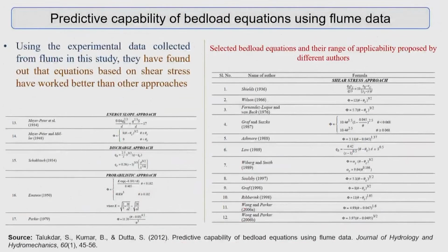Now, what are the equations? There are so many equations on bed load. If you look at the very old 1936 DuBoys equation, it is basically a shear stress based approach. There are many methodologies based on shear stress approaches, with certain assumptions. Like Grass 1998, a very simple equation, it just depends upon theta and theta c, the Shields parameter at the critical stress. Based on that we can compute the bed load.